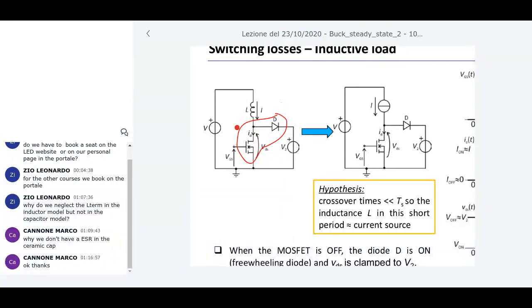For mechatronics students that follow the components and transistor lectures, this is a circuit that has already been discussed. In that case, the cathode of the diode is connected here, but the situation is always the same. Now we have another voltage supply V2, which is not V, but in the case V2 is the same as V, the circuit is exactly the circuit that they analyzed during those lectures, in which the diode is the freewheeling diode for the inductor.